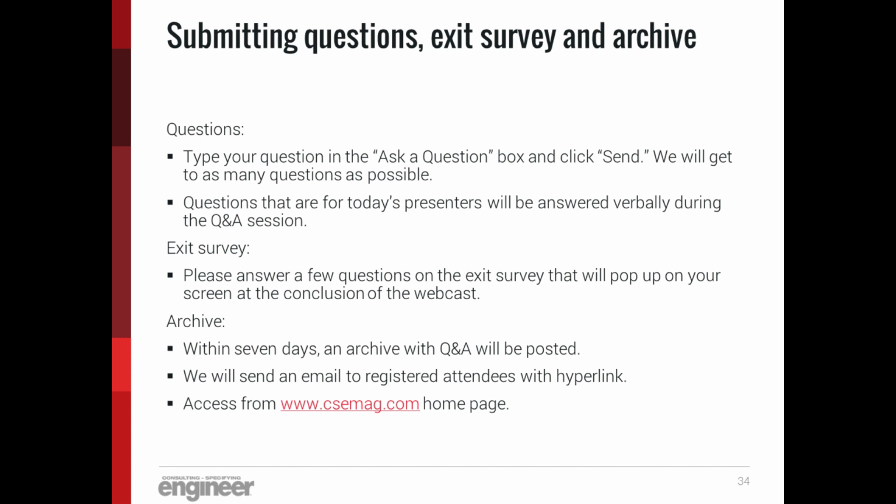So we get this a lot too. Now, when you look at, say, 517.40, when you start getting into essential electrical systems for nursing homes and other limited care facilities, you're going to see that it actually changes the figures. The figures show 2 switches instead of 1. It'll show a life safety and an equipment branch switch, and it doesn't necessarily show a critical switch. It doesn't show 3, it shows 2.